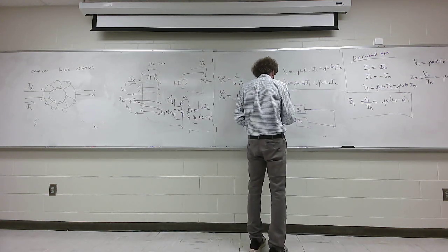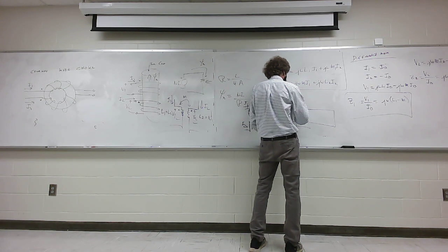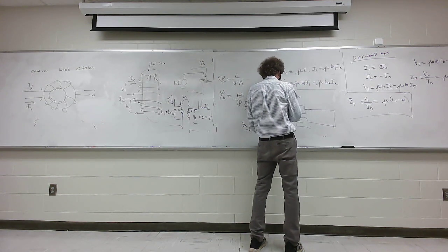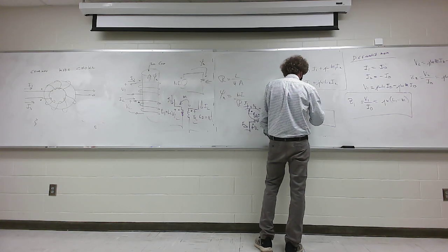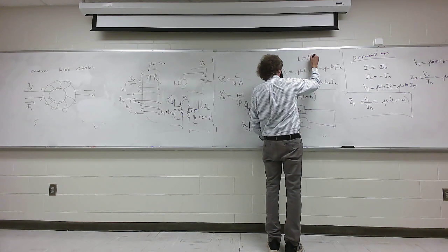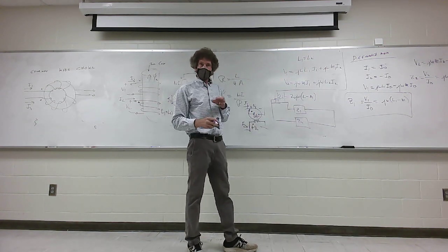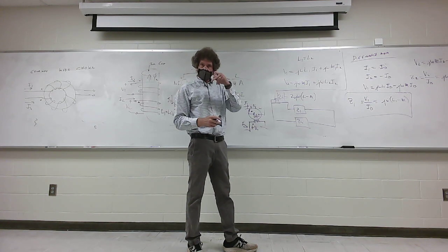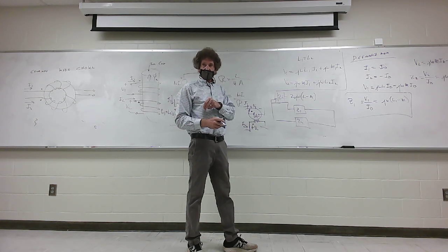If you looked at the net impedance here, Zn, it would be equal to 2 times j omega, just the magnitude of Z right here, j omega (L minus M). And here we're going to assume L1 is equal to L2, because that's the way you build common mode filters. You always have the same number of turns in the primary and secondary, therefore the primary inductance has to be equal to the secondary self-inductance, and the mutual is the same for both. Y'all follow me?